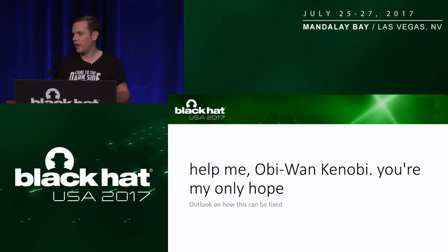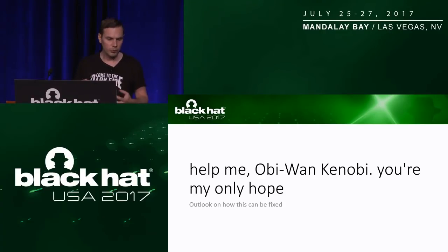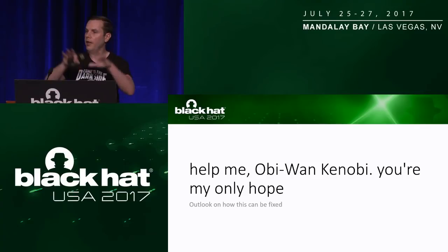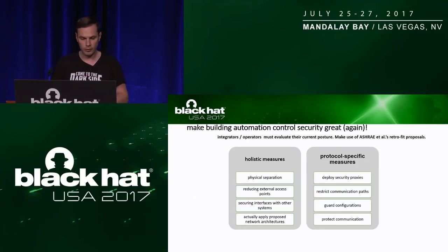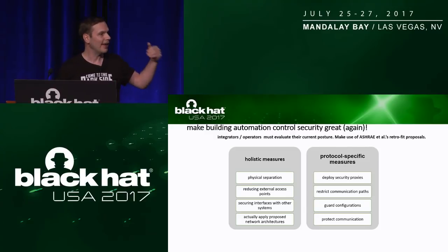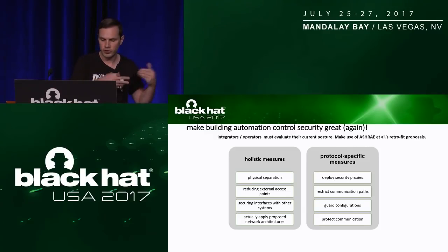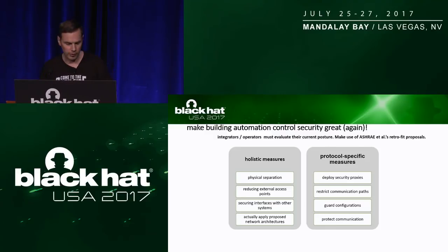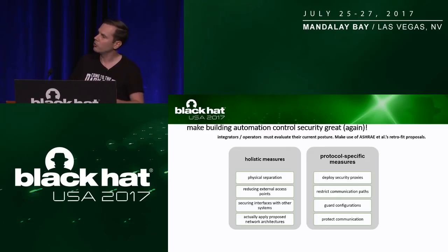So what do we do about this? I really think this presentation should be somewhat of a reminder. I didn't want to call it a wake-up call, that we still have not covered all areas with industrial control systems. I guess as always, it's both a technology issue and a people issue. Technology issue because, obviously, there are still secure by design elements missing in the current state of technology that we find in building automation control. We also still have a people issue because ASHRAE, responsible for instance for the BACnet standard, or the KNX association, have put out information on how to, I would call it, retrofit security in existing installations.